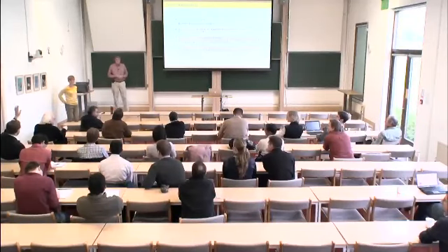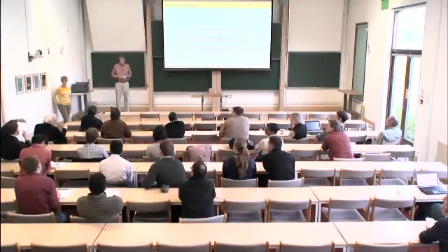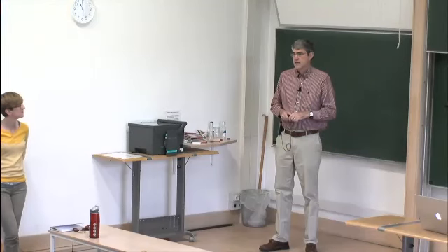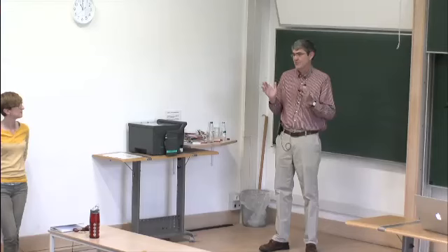Any final questions? Is there a hard-coded assumption of collocation here, or can the control volumes that you're integrating over be different for different variables? For what we're doing, we're always using the same volume for all variables. So our basic quantity that we're storing is the cell average over some fixed set of grid cells.